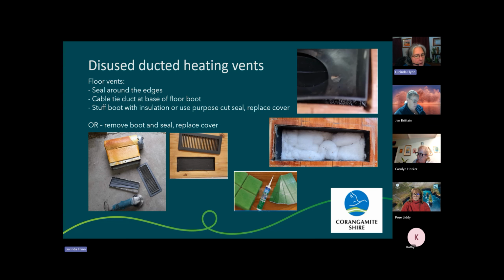Just in case you don't know what's under there, this is sort of what it looks like under your house. This would be the bit that comes in through the floorboards or through the ground or the floor. And then this is the floor boot, and that's where the duct would be connected. So most of the time you would leave that there. You might cable tie the duct over here just for an added measure, making sure nothing's getting in there and nesting in your nice insulation.